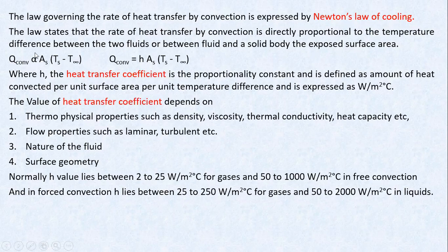If we remove this proportionality constant, we write it as h, where h is the heat transfer coefficient. The heat transfer coefficient is defined as the amount of heat convected per unit surface area per unit temperature difference, and it is expressed in watt per meter square degree centigrade.